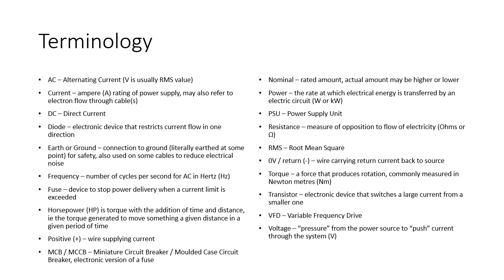Transistor is an electronic device that switches a large current from a smaller one. We do have a sort of transistor inside a VFD, but it's more of a different type of device related to a transistor. But that device is used to chop up the DC supply into a pseudo AC current. And that's one of the key components of the VFD. It's these electronic devices which do that switching of the power, and they result in your output, which you use to control the motor.